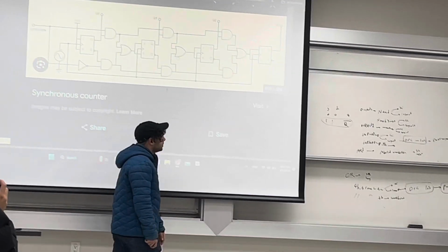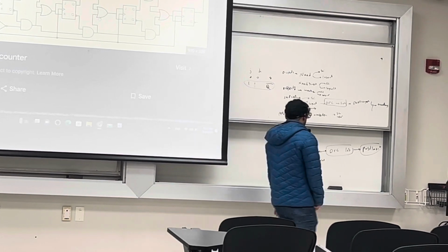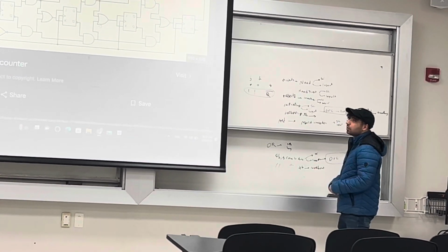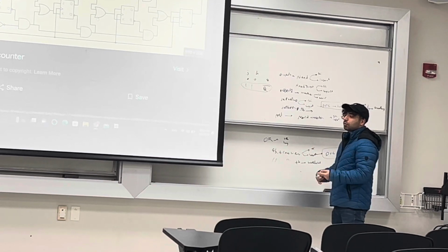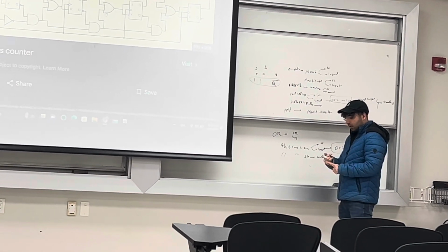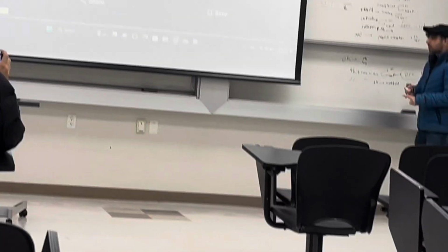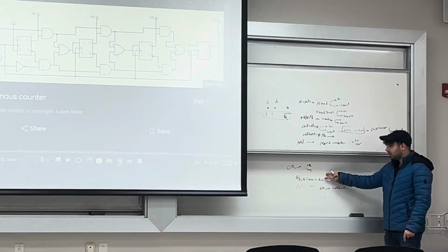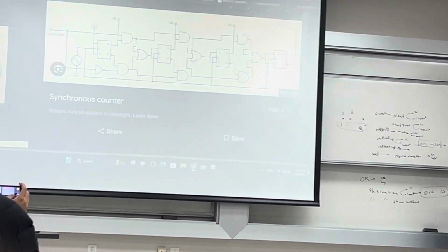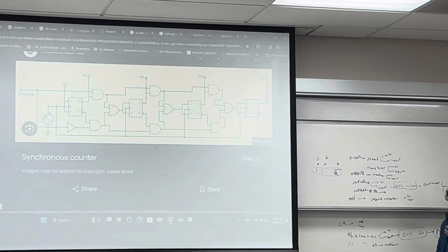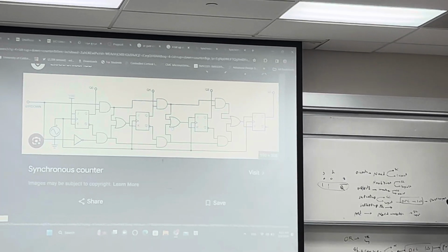That's it. So based on this design, on the output, see Q0 to Q3, and one time do the up counting and show me the result of the up counting, and the next time show the down counting. So you need to run the schematic two times, and two times you need to run the post layout. You need to show me 4 outputs on the 4-bit counter.